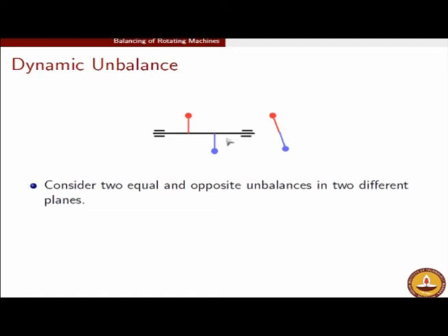So therefore it is statically balanced, but dynamically it is unbalanced, because each of these equal and opposite forces, the red and the blue one, is going to lead to no unbalanced forces, but again unbalanced moments. And to get rid of that unbalanced moment, as I said, again the bearing reactions will have to kick in, and that will in turn lead to shaking forces getting transmitted onto the frame structure.